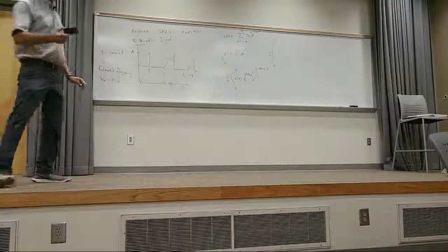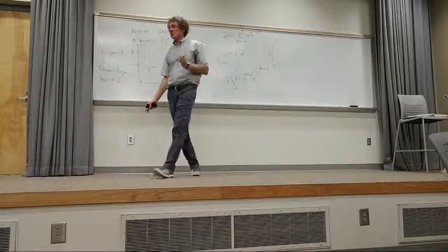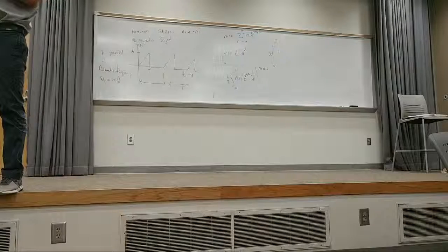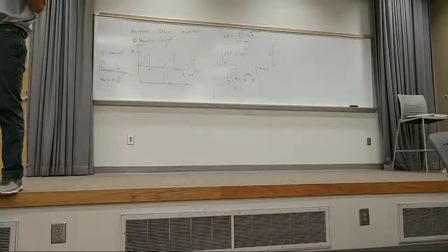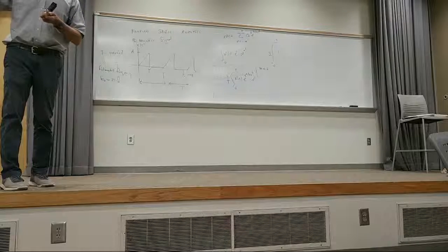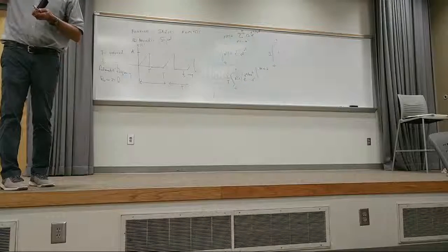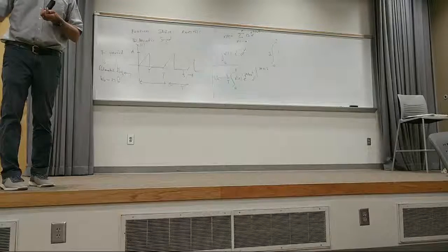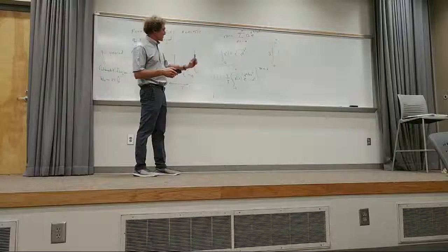You're asking yourself, why are we doing this? Which is a good question. Well, eventually I'm going to turn this thing into a series that is just a magnitude of some coefficient c of n and a cosine of n omega naught t plus a phase angle. The reason I'm going to do that is because that is the exact way we could represent a phasor, magnitude and angle, if it's a cosine varying waveform. You remember before, if you had 10 cosine of 377t plus 30 degrees, that could be represented as 10 at 30 degrees, and you would just use the frequency 377 to calculate the impedances on the inductors and capacitors in your system, and you could solve the network, right? That's why we're doing this. Just so you know, it's not all for driving you nuts. That's the real reason, the motive.